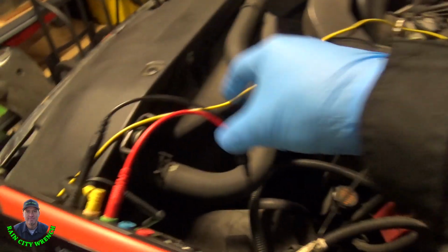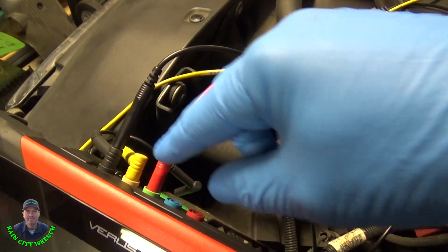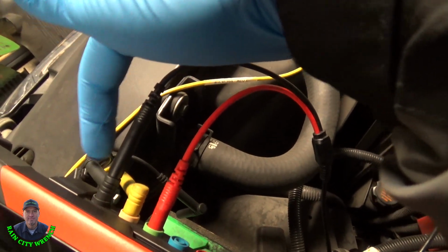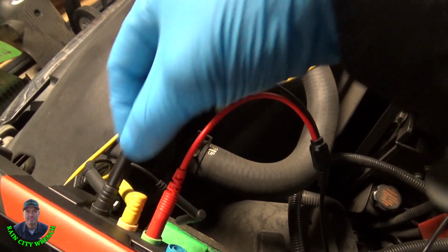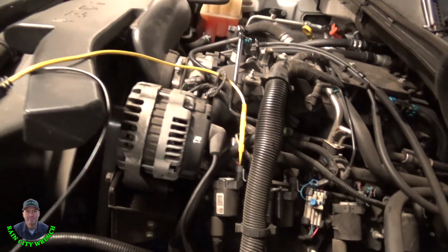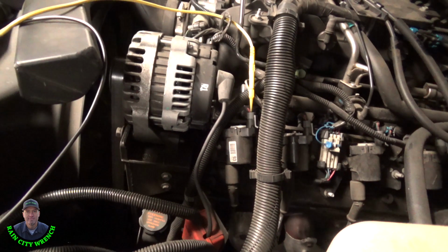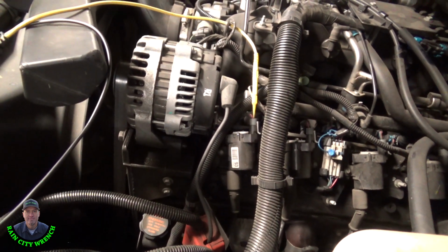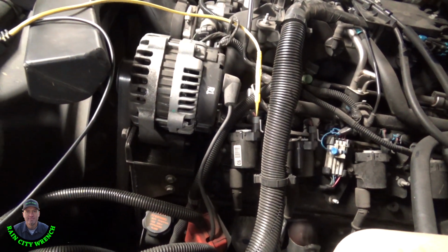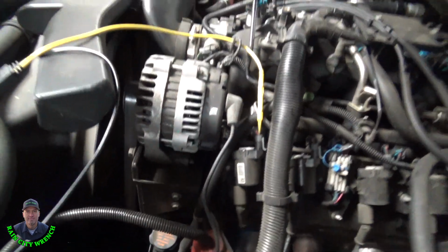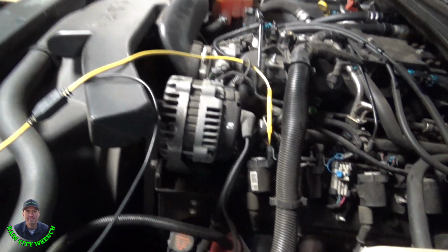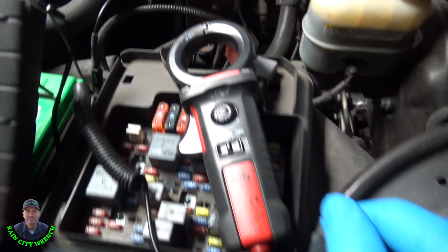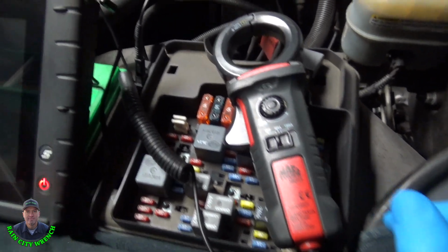And it goes over here. I've got this on channel 2, the input, and I have channel 1 ground and that combined together. And I still have channel 1 connected in to my coil, because the test after that, we're going to use this trigger to do a relative compression test with my trigger on my #1 coil and this high current amp clamp. So let's get started.